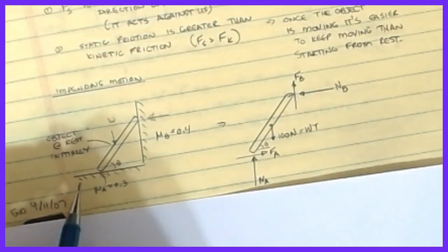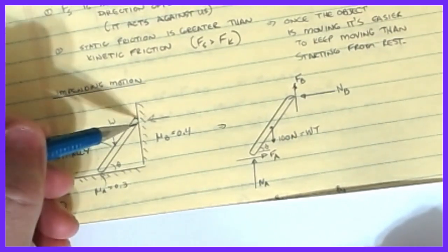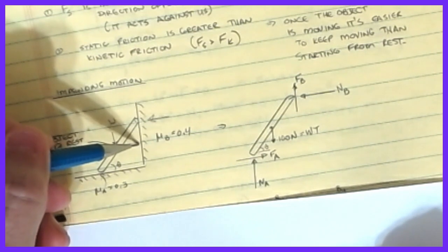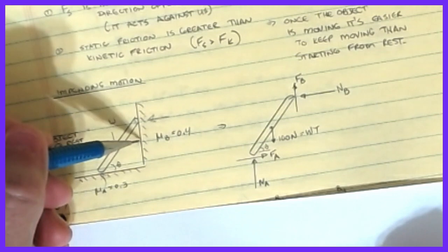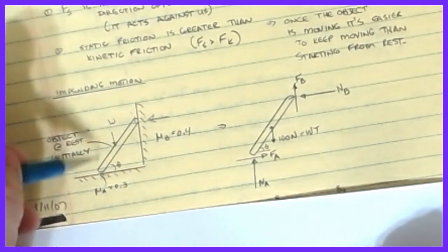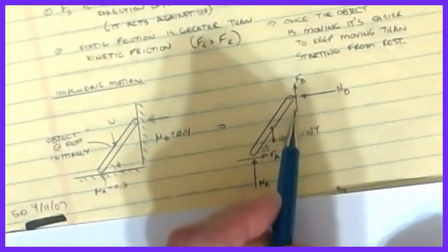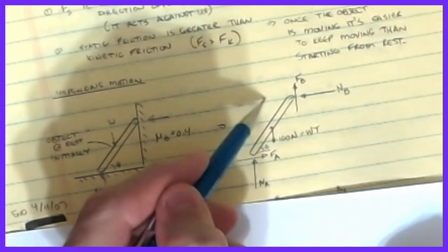Okay, so if we look at that and we try to draw, well, what does the free body diagram look like on there, we can look at something like this. Obviously, if this ladder ever starts to fall down and gravity is acting down, then this point wants to move downward. So the impending motion of this point for this interface is down, which means the friction resistance value at that point has to be up. I'm calling this point B, and I'll call the other end point A. At B, we had that normal reaction, and then I have this vertical force FB. That's because the impending motion of this point was acting downward. We have the self-weight on this.